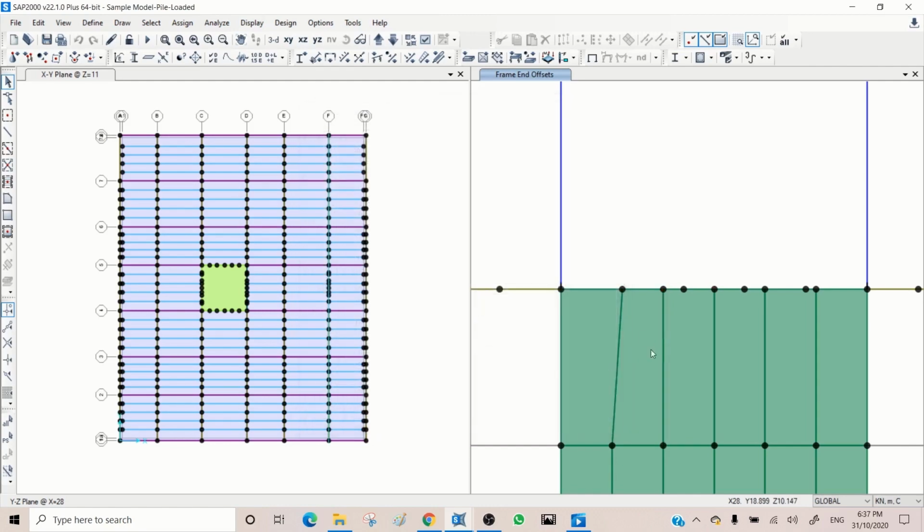It's not subdividing, it's just meshing the shell. So see how it works, because as I explained before, if you want to put lots of meshes and lots of elements, that just increases the stiffness and mass matrices, and that will be more time consuming during analysis. So you can use the mesh like what I did, and you don't have to do anything else. I have one wall meshed, one wall connected by beam, and one wall I didn't do anything. Let's see what's happening after analysis.